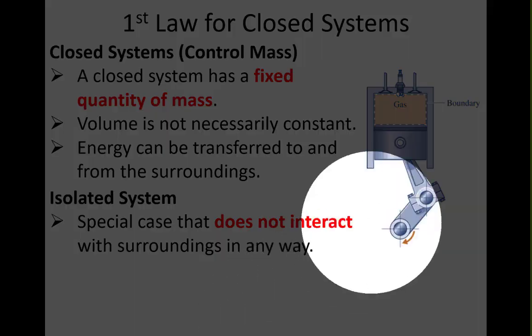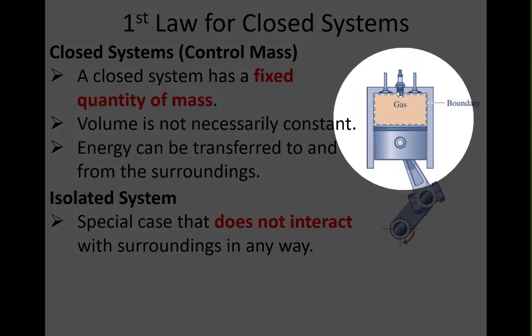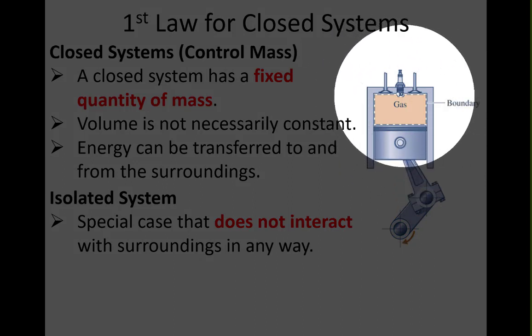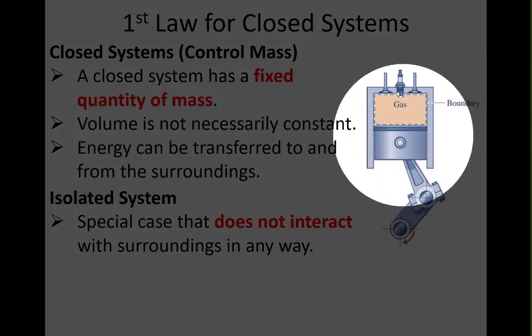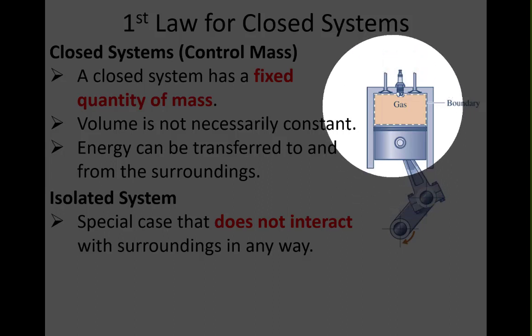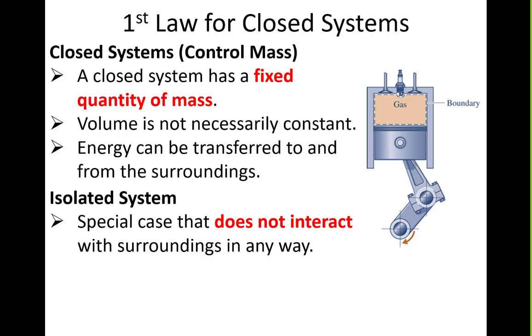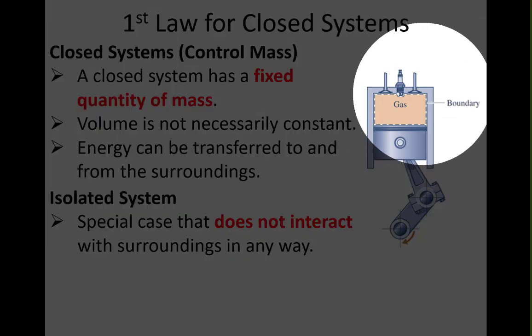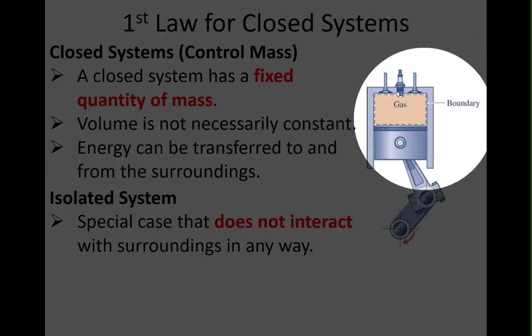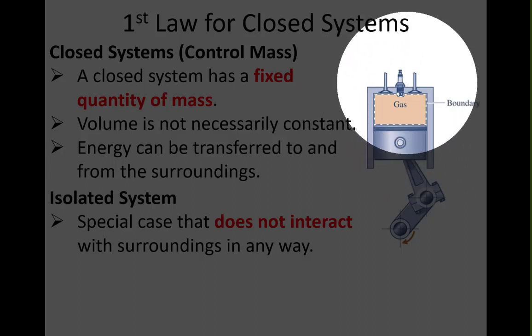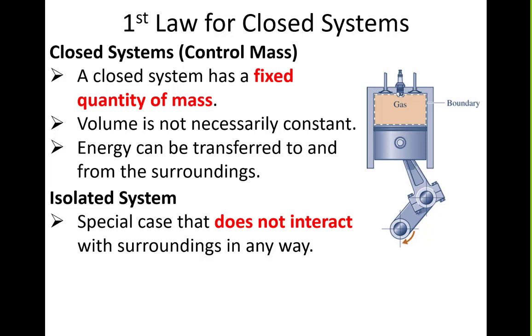You'd see this in a piston cylinder assembly when both the intake and the exhaust valves are closed. Now, if this piston moves up, then it's compressing the gas. But if the gas is expanding, like after the spark plug ignites, then the gas is expanding and pushing the piston down. And none of that really works if these valves are open, because then the pressure in the cylinder would just be basically the same as whatever's outside the cylinder.